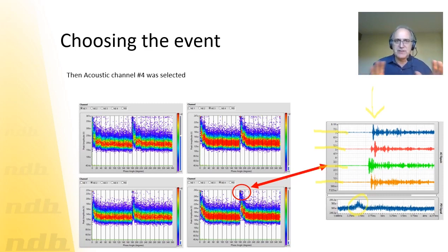You need to sit down, you need to think what is your next move and take your measurement the best you can, because when you're going to leave the substation, it's done. You cannot come back and you need to come back with an answer. So in this example, I tried all suspicious events on the HFCT, and then I came back, I said, I'll try acoustic.